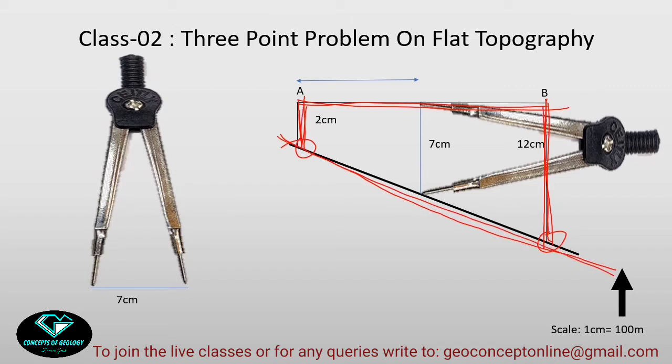To find out the 700 meter borehole, I need to draw a 700 meter line here, that means 7 centimeter according to my map scale. I will copy this line with my divider, and I will place the divider in this construction to find out where the 7 centimeter line is fitting. Suppose it is fitted here. I need to use a hit and trial method to find out where the 700 meter is exactly fitted. So suppose this line is fitted here, then I will measure this length with my ruler, or better, copy this length with the help of this divider again.